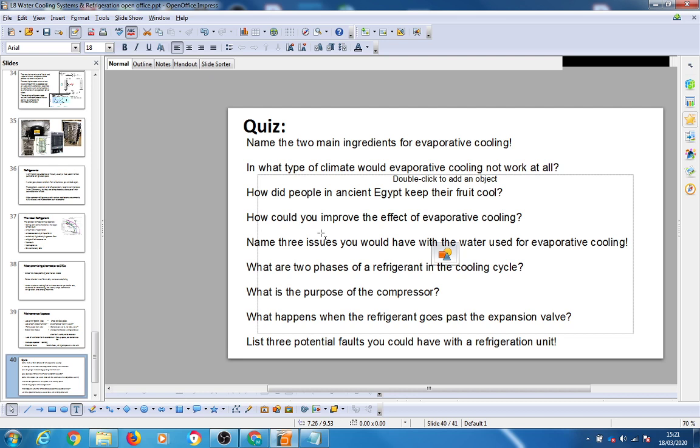Josh, can you elaborate on that? Bacteria, scaling, mechanical issues, oxygen in water. Yeah, thanks, Aaron, for that. It's too humid, okay? Yeah, that's the thing. Evaporative cooling doesn't work if there's a high level of humidity in the air, and it's a problem.